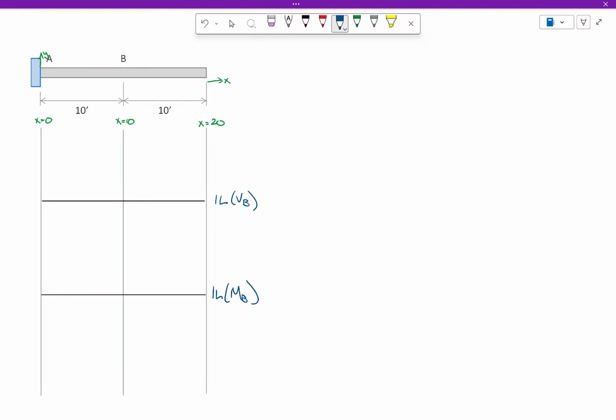Okay. All right. So let's take a look at the influence line for the shear at B. So what do I do? I put a shear release in. Okay? I used some terminology yesterday that I told you I was going to clear up. We say this goes down, this goes up. But I didn't say that. What I said was the left side tends downward. The right side tends upward. Right? You know what I said?